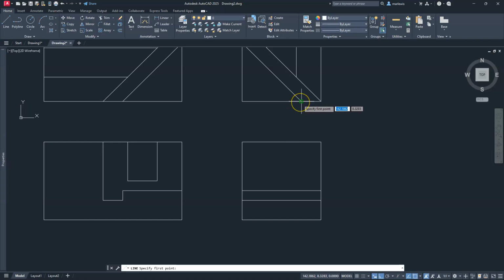I'm just going to draw a line. I'm just going to touch that, come straight down to here, and where it intersects, I'm going to do a left click here, down to where it's perpendicular here. Okay, let's go ahead and trim this portion off. So I'm just going to go to trim. I'm going to take away that portion and that portion.